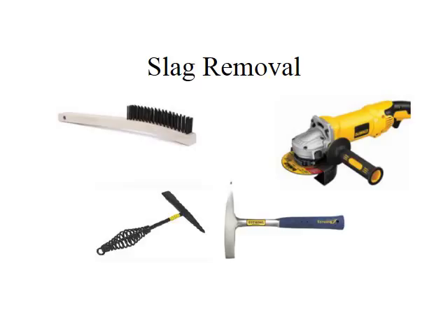Slag is not a part of the final weld and thus does not contribute to the strength or protection of the metal after the welding process is complete. Slag is a waste material and needs to be removed. Removal of the slag is necessary for 4 reasons: visual and NDE inspection of the weld area; aesthetics or visual appearance; if a second layer or pass of welding is to be made on top of the first; and to provide a clean surface for coatings such as paint or oil.